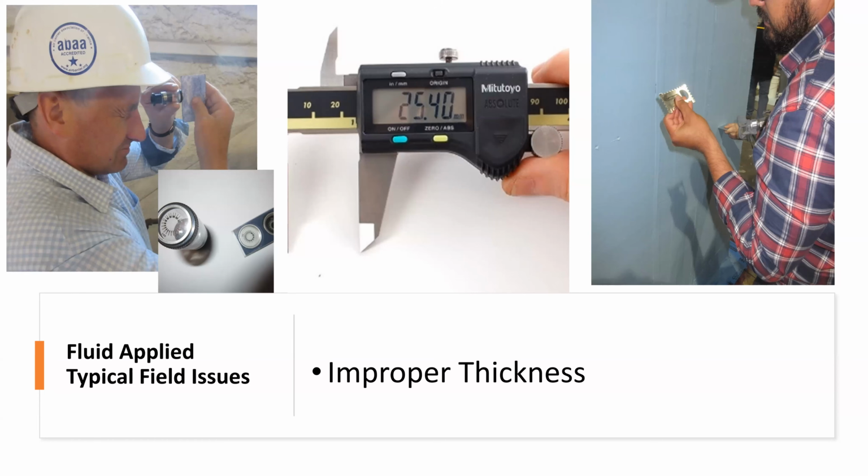Some of the challenges with thickness testing are that sometimes the fluid is stuck so well that you'll end up ripping off the face of, say, the exterior gypsum board. That can be a challenge because you're now testing the thickness of two things, not just one. So you try to scrape off the substrate as best you can. Option two is you can find out the thickness of that facer, do the thickness testing of everything, and then just subtract that facer. So this is fairly easy to do during construction and also after.